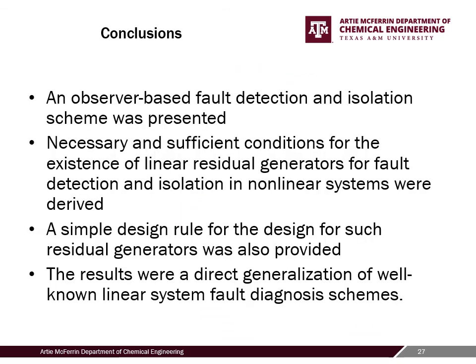Coming to the conclusions, an observer-based fault detection and isolation scheme was presented. Necessary and sufficient conditions for the existence of linear residual generators for fault detection and isolation in nonlinear systems were derived. A simple design rule for the design of such residual generators was also provided. And the results were a direct generalization of well-known linear system fault diagnosis schemes that are present in literature.